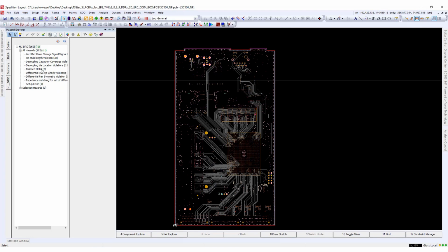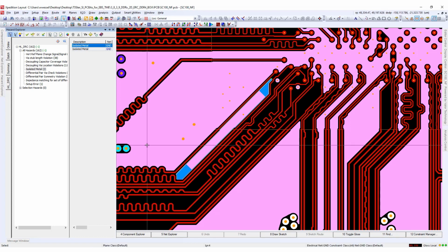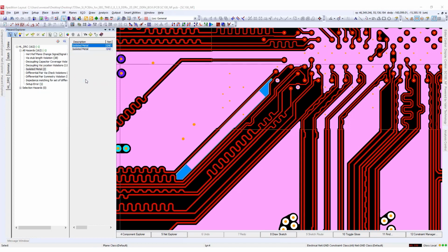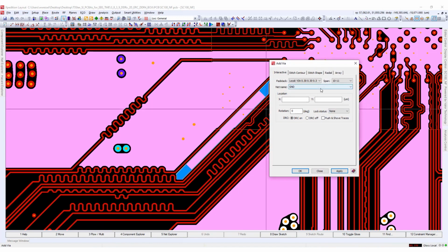Based on the metal island issue, I want to show how a typical issue review and fix could look like. With cross-probe enabled, I select the first item in the list. The main screen instantaneously fits the screen on the position of the error. In this case, we need to add a wire on both ends of the plane, to avoid that this plane could act as an antenna. The area where the wires should be placed is highlighted, and it is very easy for me to do this even without being an EMC expert.